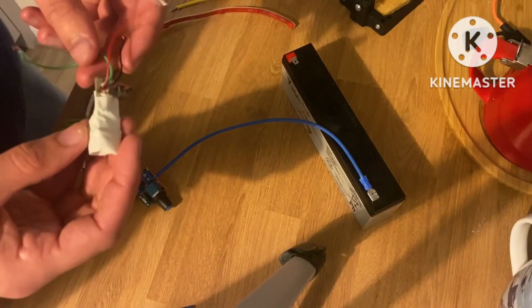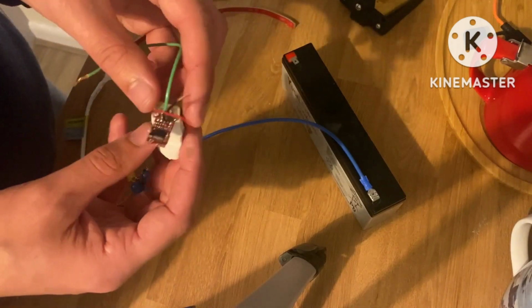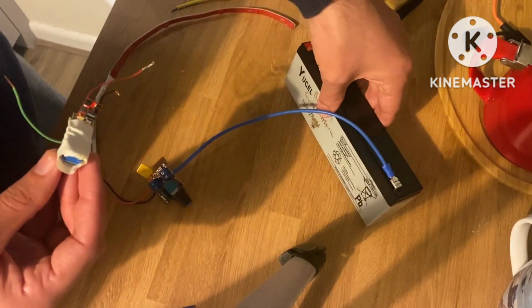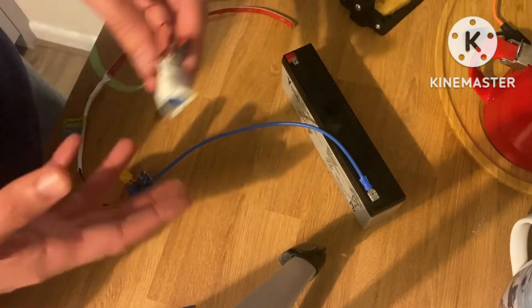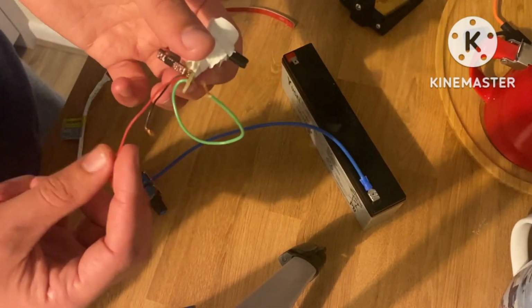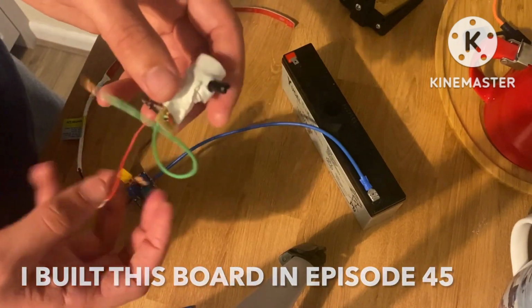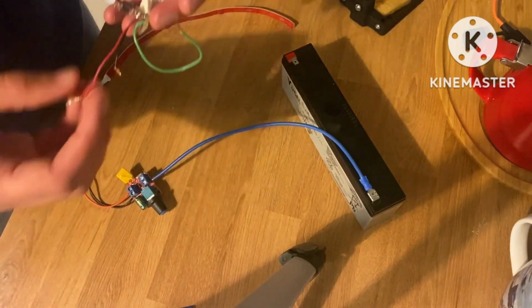So the next thing we're going to do is add the power supply board. This is a board that just limits the voltage that comes from the battery. These batteries kick out about 12 volts. When they're fully charged, they might be a bit higher than that, around 12.56, whatever. What this board does is it takes that 12 volts and regulates it down to about 11.1. And there is a reason for that I'll go into in a bit more detail in a second.